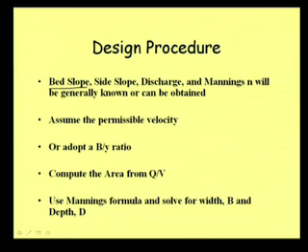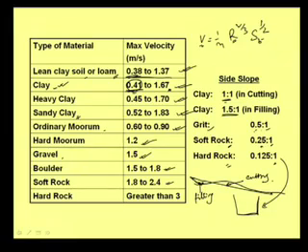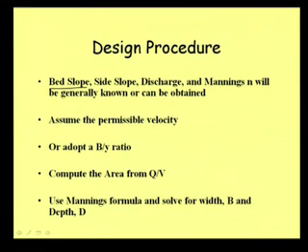And what will be the design procedure? Say bed slope we will be getting from the topography, as I have explained. We have very small scope of manipulating that. Of course, we can do it, as I was showing here, that say this can be the slope, we can have this slope also by cutting. We can have this slope if we fill up this portion. So slight manipulation is possible, but grossly we cannot change the slope. But still, bed slope we will know from the topography.